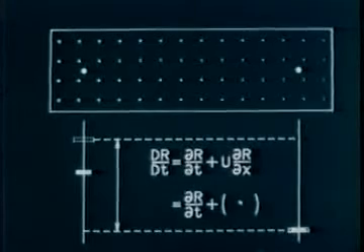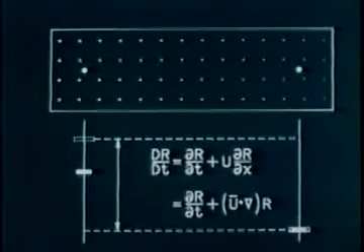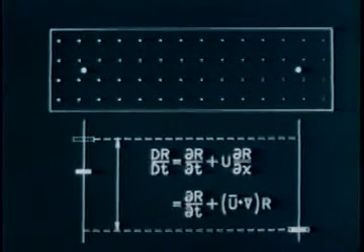We're also interested in the material derivative of a vector field such as the velocity. We're especially interested in that because the material derivative of the velocity gives an expression for the acceleration in a form which we need for the momentum equation. The expression that we just obtained for the material derivative of a scalar field would work just as well for each component of a vector field, but we can also show the material derivative of the vector field directly.